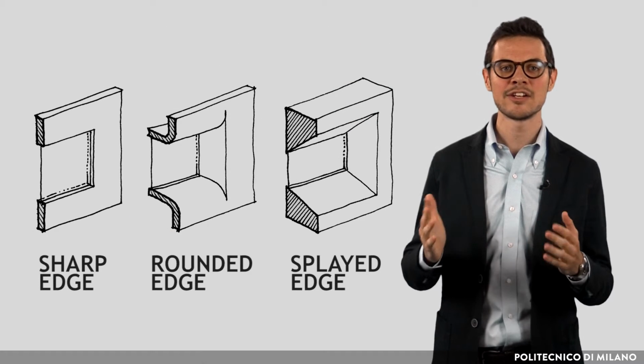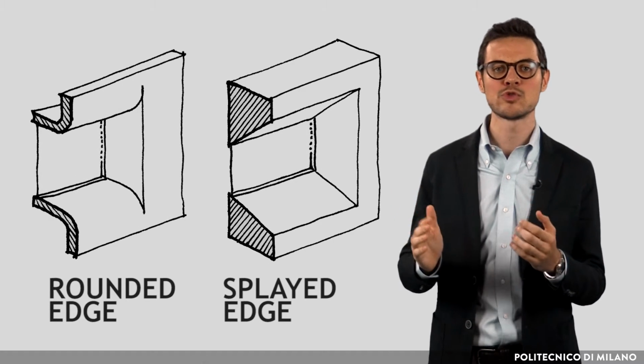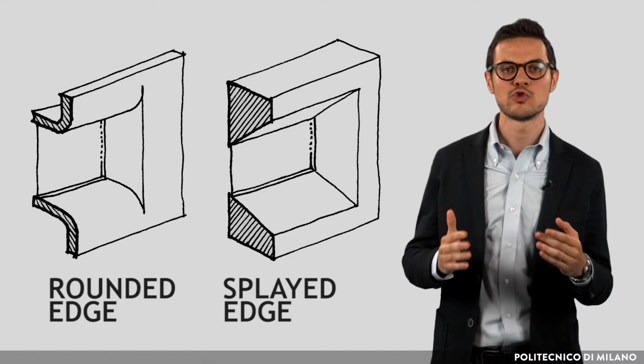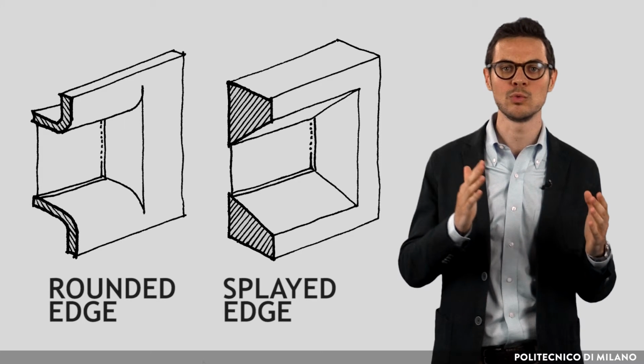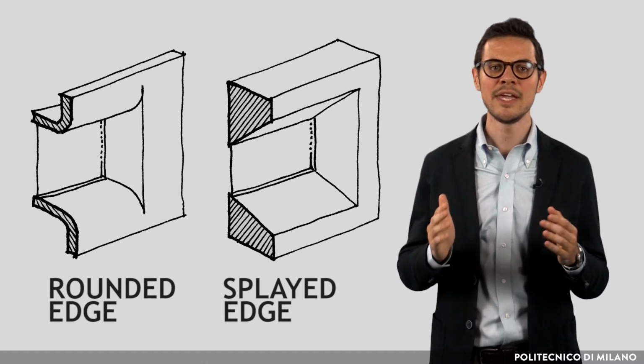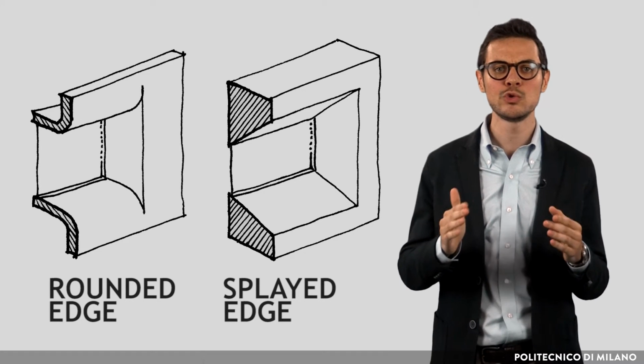After that, designers should remember that sloped surfaces around windows help to soften glare. These surfaces should be light-colored and provide an intermediate brightness between windows and room surfaces, making an easier transition for the eye and reducing eye fatigue due to the contrast of luminance. Finally, it has to be noted that it is important not to waste glass surface where it cannot bring any benefit. It wastes energy and causes discomfort.